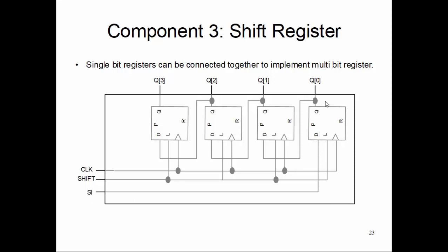So SI is connected to the LSB side of these 4 registers, and values are trickled down in a daisy chain fashion through the registers. They are connected in a daisy chain fashion. So what happens now? You can selectively start shifting the incoming bit pattern through this chain of flops, and you can observe all of those values, not just the last MSB stage as a scan out, but all the outputs, and make it a 4-bit information for some other modules if you need it.